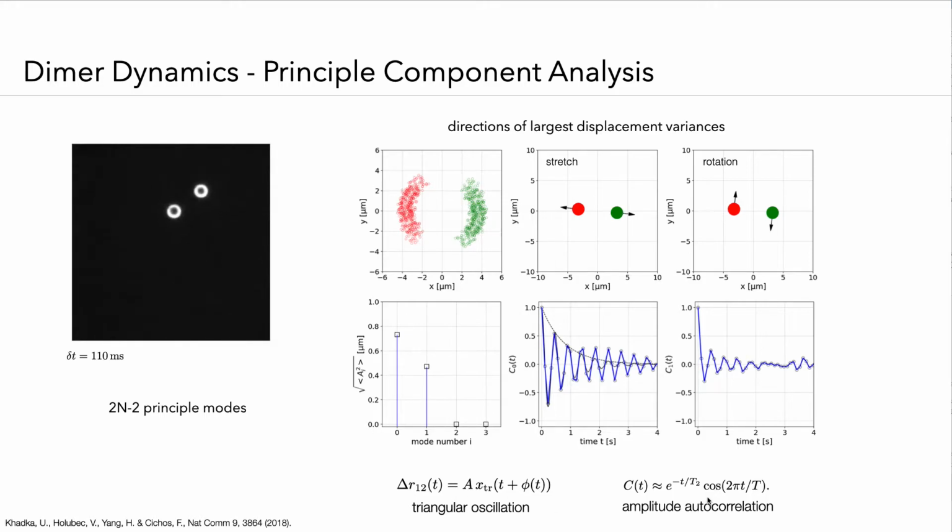So first of all, this is only an assumption, but if you look a bit closer at the Fourier spectrum of a triangular function, you will see that it contains a sum of odd frequencies, where the lowest frequency is the one given here. And so it is a reasonable assumption that this is the only frequency which really contributes to the autocorrelation decay. Okay.